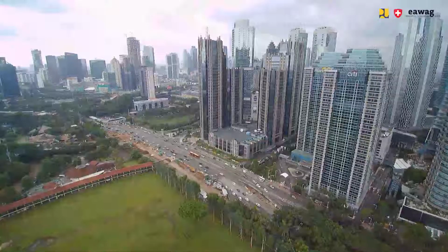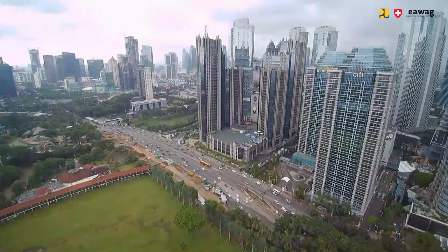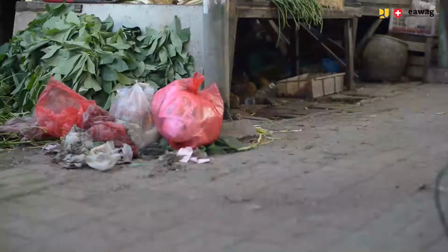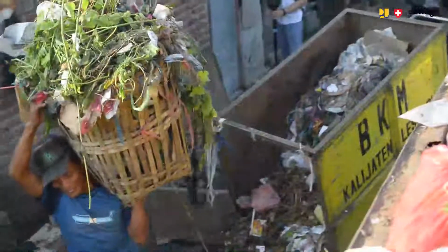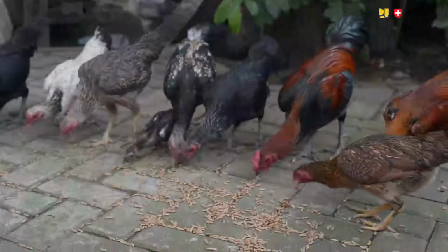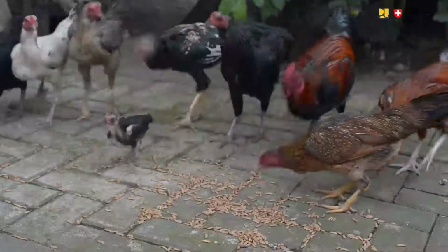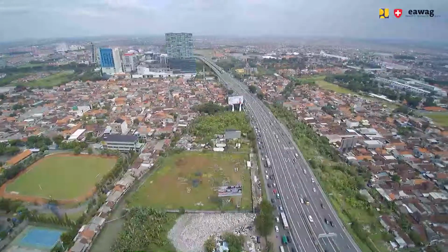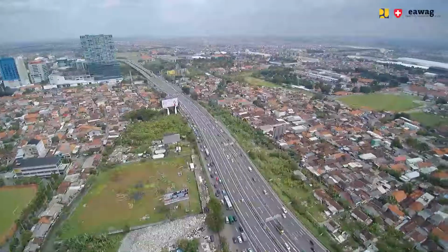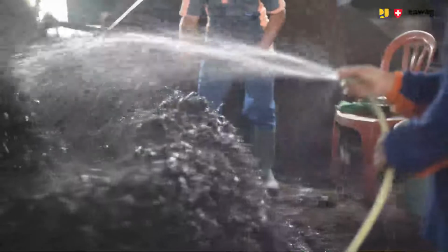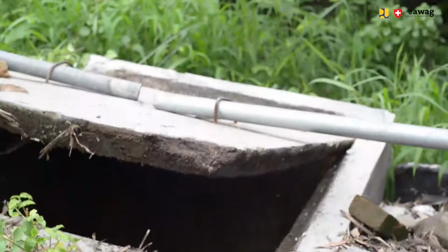The first thing we're going to look at is what aspects are important when looking into selection of the site location. First of all, we have to make sure that there is availability of a nearby source of biowaste in sufficient and predictable amounts. Then we have to make sure that the customers for the fresh larvae and other markets for post-processed products are not too far away from the site. Then areas where adjacent land users may find a waste processing facility inappropriate should be avoided. We also have to make sure that water and electricity supply is available at the site and that there are wastewater treatment facilities available.